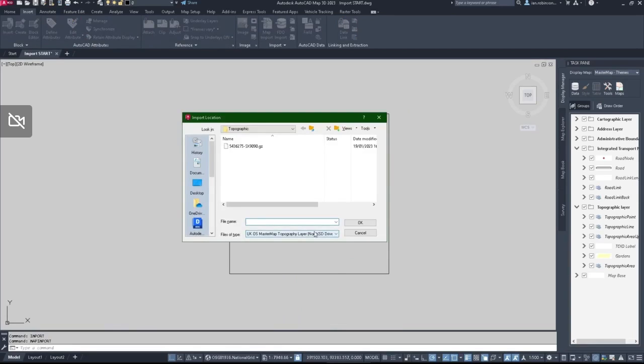And you can see in here we can import Autodesk SDF files, which is spatial data files, or Esri shape files, MapInfo files, they're quite common, TAB files or MIF/MID files. We can also do all the OGC stuff, so that's the Open Geospatial Consortium. So KML, for example, Keyhole Markup Language, it's just a markup language like GML. We can import all of these as well.